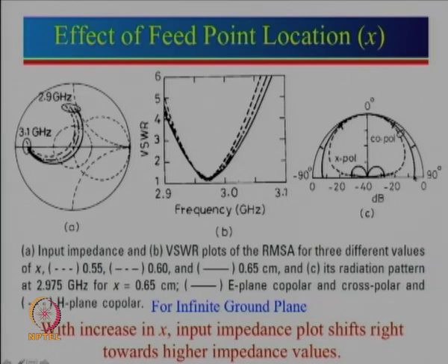So, you look at the slot antenna. Slot antenna will have an omnidirectional pattern. So, let us say we have two slots here, there is an omnidirectional pattern here, omnidirectional pattern there, but below there is a ground plane. So, it will not radiate in the downside. So, the pattern will be something like this, pattern will be radiating in the upper hemisphere.